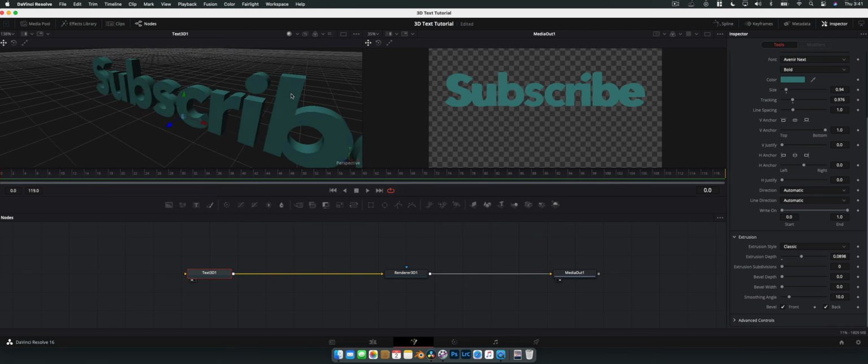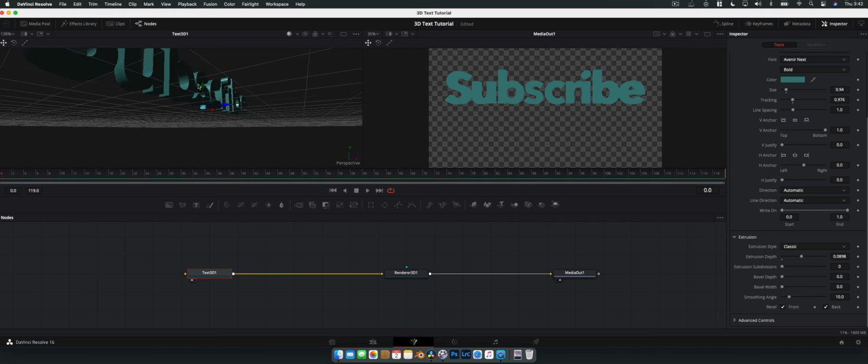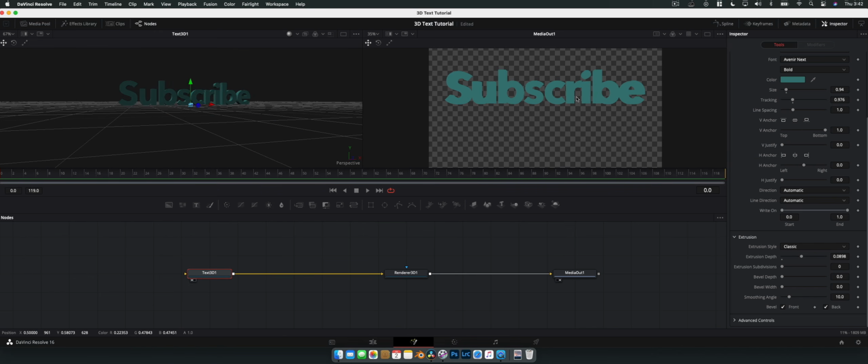There we go. All right, so this is giving us a good idea as to what the text looks like in 3D space. The thing is though, in this viewer, we're seeing some shadows and we're getting a little bit of that 3D pop there, but we're not seeing it here in our media out node. Why is that? Well, it's because we don't actually have a light built in. So what this viewer is showing us is just the default lighting, just so that we can see what we're working with, but we don't technically have a light in the scene. And that's why the media out node is just getting a flat image with no depth whatsoever.